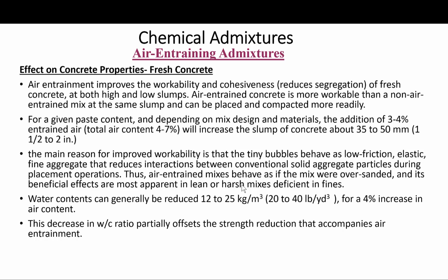The improvements in workability are such that air-entrainment may be used even when freeze-thaw protection is not required, because of this workability. So this is particularly beneficial when mixes have low cement contents, poor aggregate grading, or harsh aggregate texture. So in this case, we use air-entrainment to help produce more uniform, well-compacted concrete. Okay?